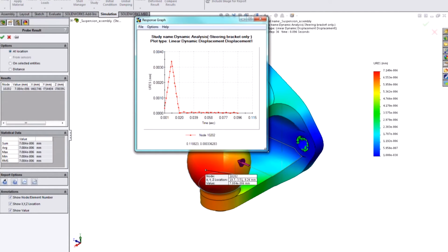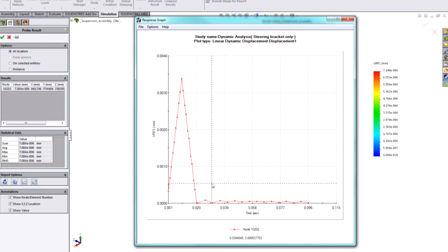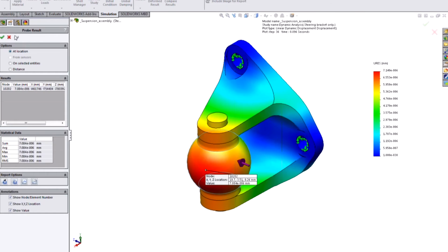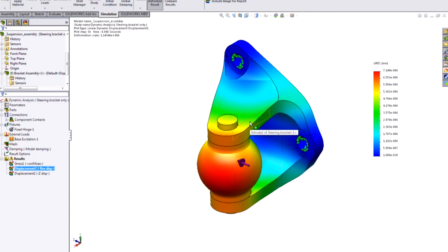This is basically the displacement versus time curve of a point in the model that I just picked randomly. So a large initial shock, see the peak value there, how much it's going to move at its peak, down to some kind of low-level vibration that dies out. And so we can look at that both in the time domain, like I've just done, and also in frequency domain, which is typically how we look at vibration.